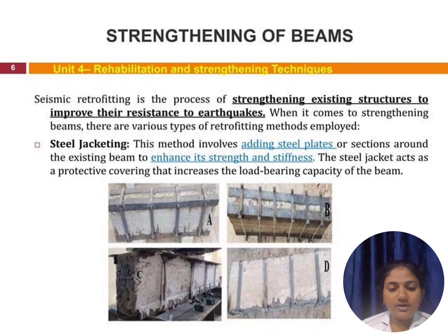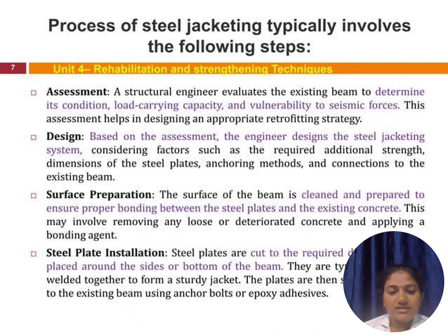And then we are coming to the steel jacketing. We are providing additional steel plates or sections to the existing beam to enhance its strength and stiffness, and it increases the load bearing capacity of the beam. And assessment is based on the design where the load carrying capacity is vulnerable to seismic forces, and design is based on the assessment of the steel jacketing system and surface, whether we have to clean or prepare it to ensure the proper bond between the steel plates and the existing concrete.